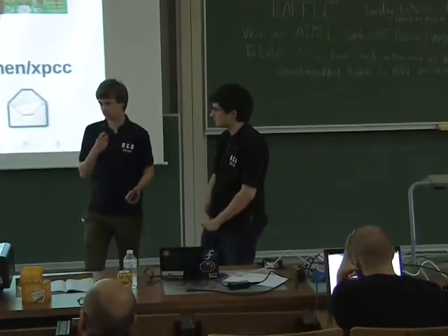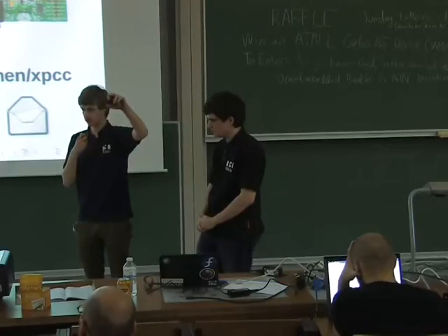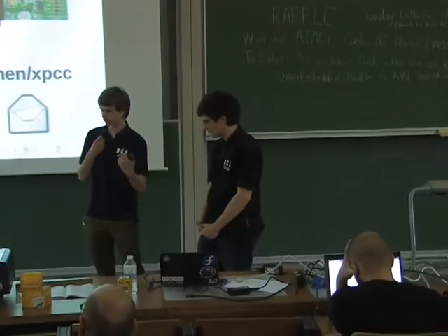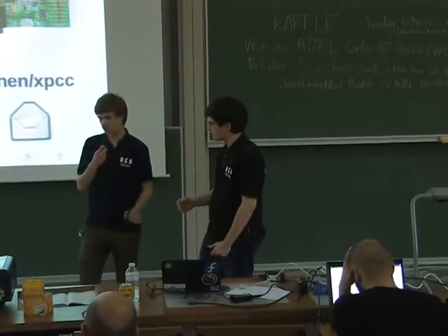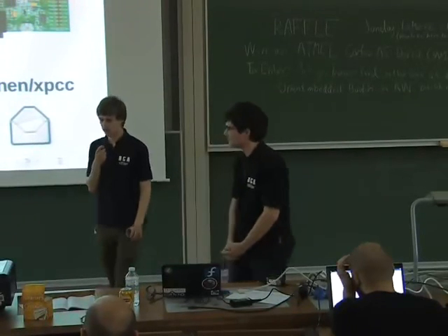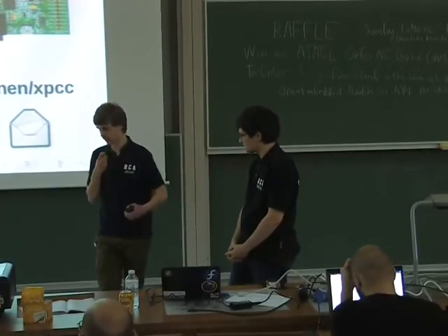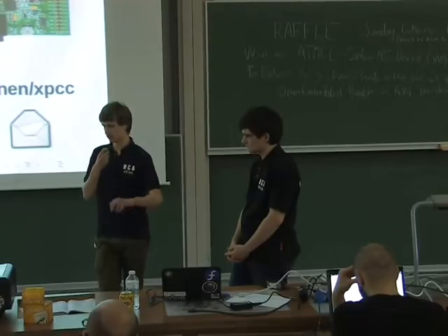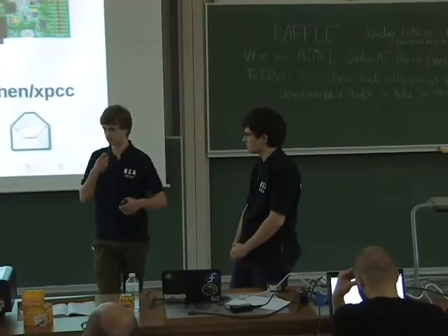So every method is on its own. There's one configuration register, so for the calls after the first configuration, you have to read back the configuration register, change the value that you want and write it back. So there's a little bit of overhead in code size. For example, it added 65 bytes. But especially the critical stuff, the things that are called a lot of times, for example the GPIO set and reset, that actually just compiles away. We put a lot of stuff in header files, which does not necessarily benefit compile time, but it's not that much, so it doesn't really matter.